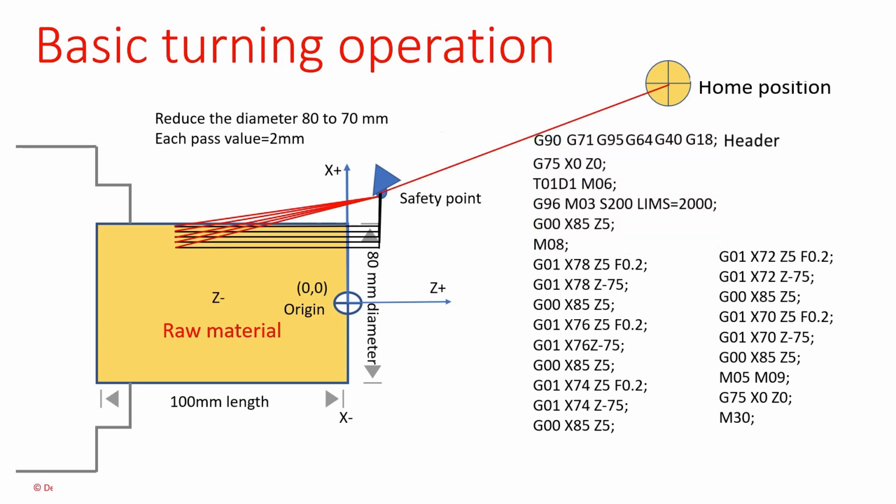Next, the shaper. In the shaper, we are creating our required toolpath. In the shaper, we are using 2 types of G codes, G01 and G00. In non-cutting areas, we use the G00 code, and we use the G01 code in cutting areas.